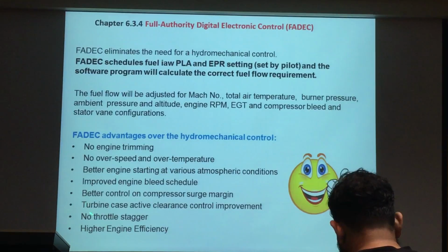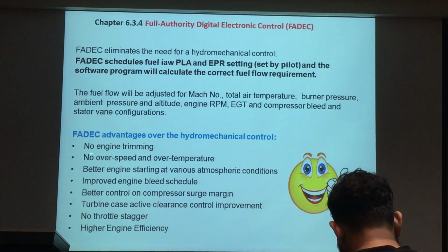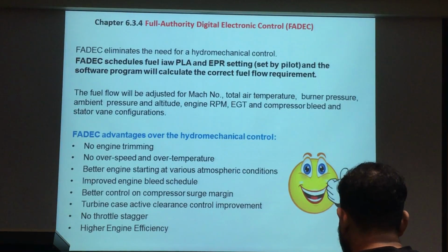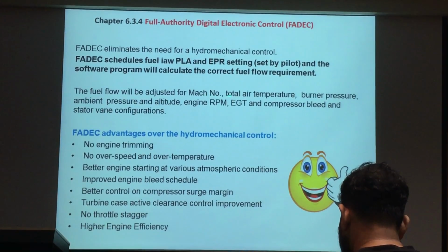So what are the advantages? There are advantages: no engine trimming, no overspeed, no overtime. FADEC schedules fuel flow in accordance with conditions. The fuel flow can be adjusted for Mach number and total temperature.